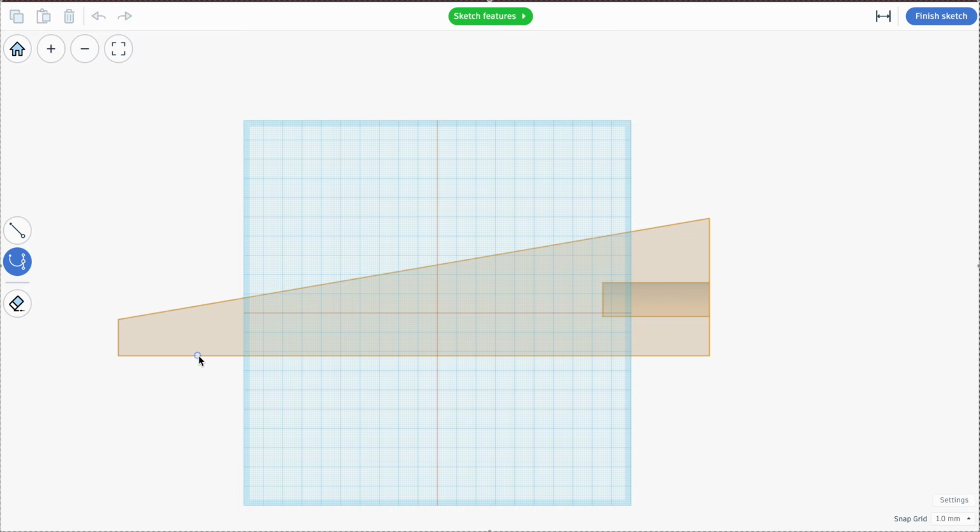So normally, what will happen is I will click on where I want to start my curve. I will click on where I want to end my curve. Sorry, let me do that again. I made a mistake there. I will click on where I want to start my curve. If I hold down Shift, it actually makes it straight, whether I'm going sideways or up.